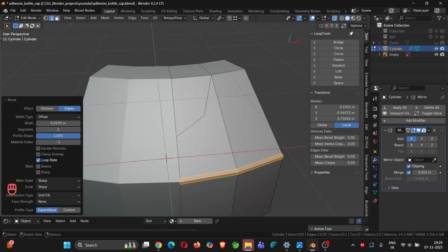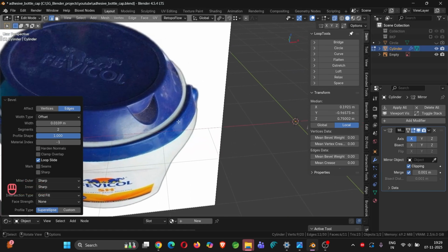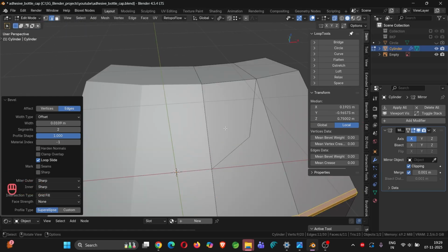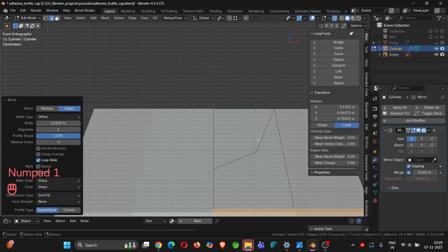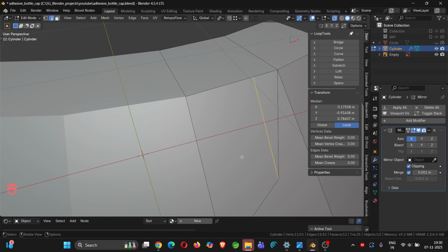What I'll do now, if you recall that reference diagram here, I need to cut that groove. So how to do that? It is very easy to do. I'll first go to this perspective, use the knife cut tool, enable that, press the A key so that it keeps that angle constant. I will just cut it. Okay. Now look at the magic of what I am doing now.